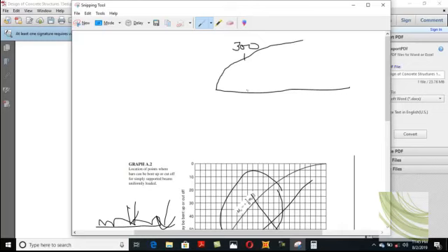So the bar which is right here must be continued for a distance of LD, because it will support the moment capacity. It will give you 300 capacity when the 4 bars are inserted into the concrete for a distance of LD.